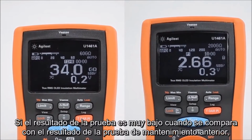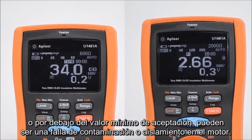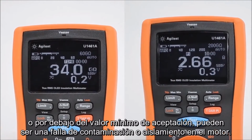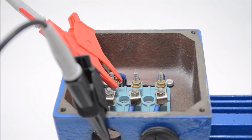If the test result is very low when compared to the previous maintenance test result or below the minimum acceptance value, there may be a contamination or insulation fault on the motor. Repeat the test with each single phase to ground if the result is not satisfactory.